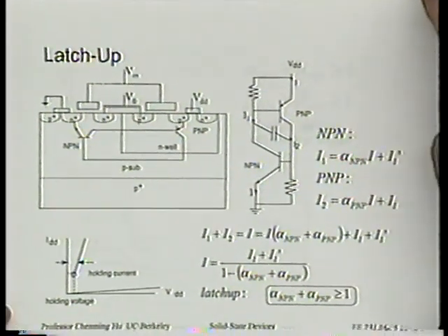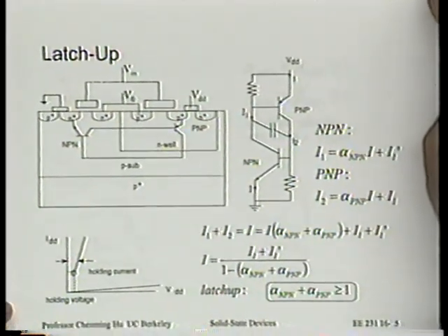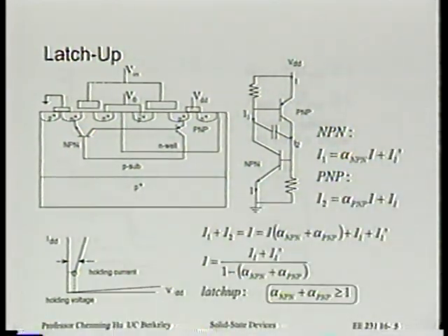All right. So let's then move to a different topic. This topic is not in the textbook. The textbook did not talk about latchup, but I think it's important that we mention this in this course. And I mention it at this point because latchup only happens when you have NMOSFET and PMOSFET together on the same chip, namely in CMOS technology. And in fact, these two types of transistors have to be close to each other. That's where you have a potential vulnerability to a phenomenon called latchup.